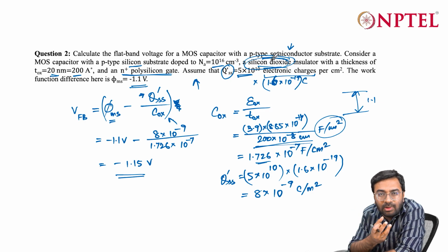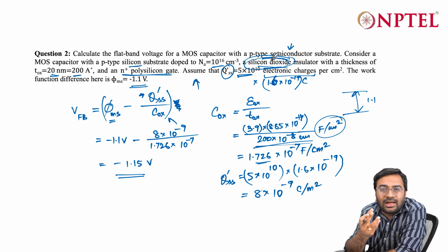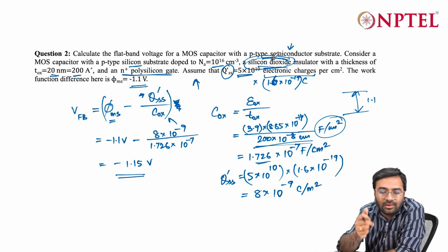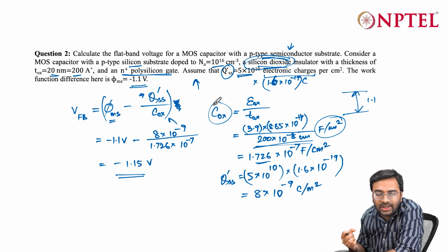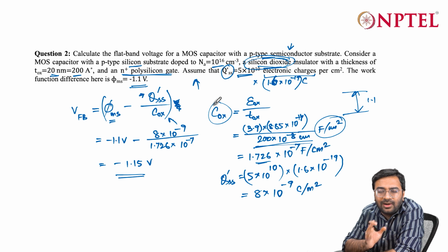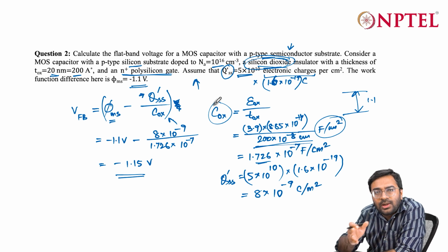So, this probably would be a sensor which can detect gas, because the more the concentration, the more will be the absorption, and the more will be the change in MOS capacitance, this C_ox value. And if you can actually get this value out as an electronic output, then you can calculate the concentration of the gas in that particular environment, something like that. So, these are some critical thinking that can convert a conventional device to an electronic sensor.